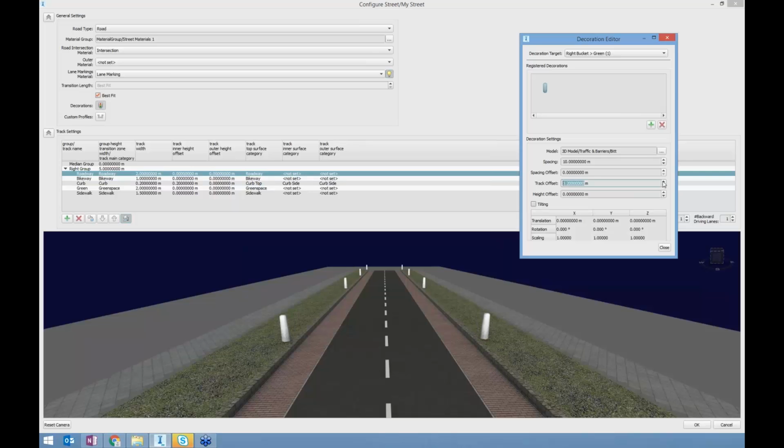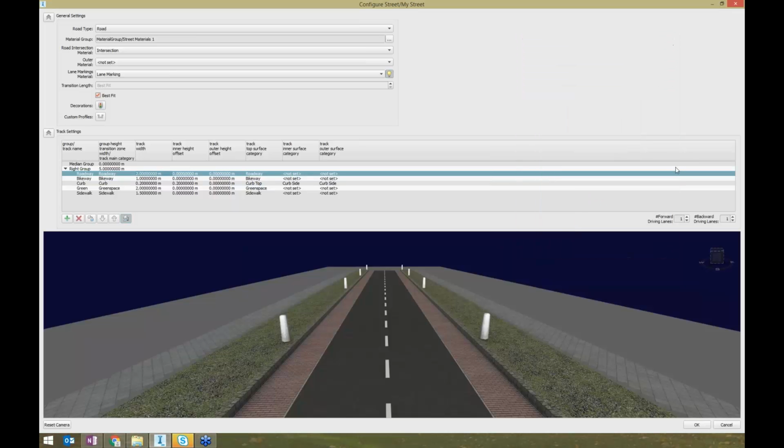And it's always a little bit of trying out, so you click it, you see what happens, and you can do a height offset if you want it a little bit lower or floating. The spacing offset is also something you can do, and the spacing itself. That all looks good so far. So I'm done with it. So that's my road so far. And let me click OK.